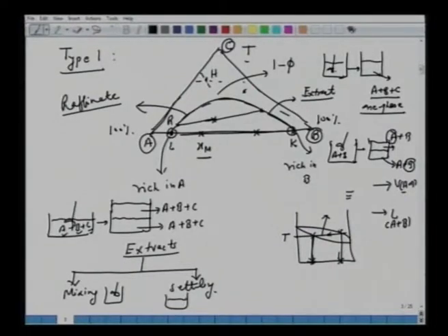So you can make the same analogy with the vapor phase and liquid phase. The more volatile has gone here, the less volatile has gone here. Likewise, the component more soluble in B as a solvent has gone here, and less so here. So there is phase separation. You can call them R for raffinate and E for extract. This is your mixing point, M. Let's take another point here. We have another mixture, allow it to mix first, then settle. You get another tie line, not necessarily with the same slope. So again we have another R and another extract.